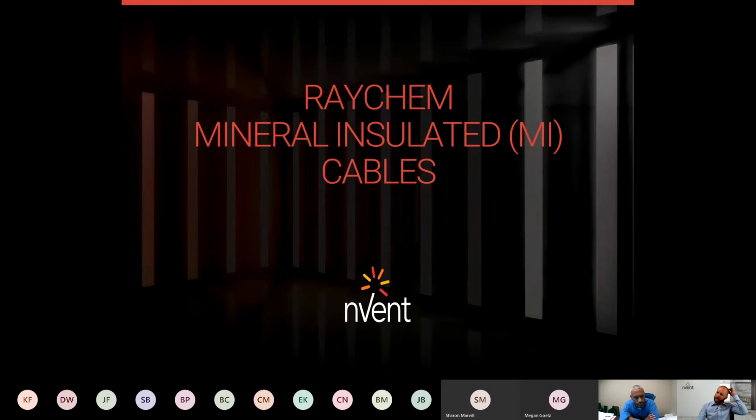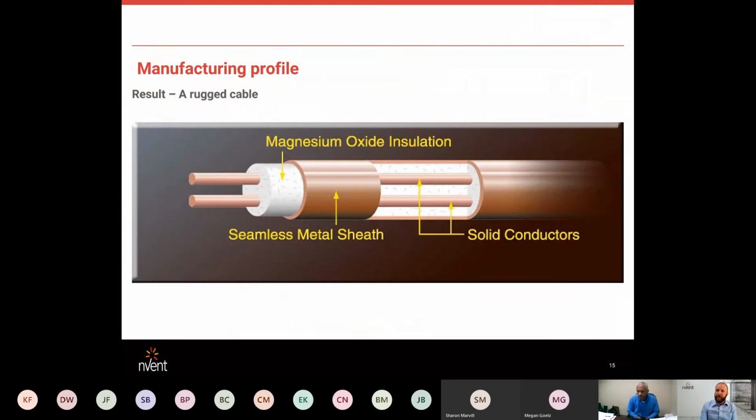So MI cables, which I just mentioned, MI standing for mineral insulated. There's a magnesium oxide insulation inside this tubing, I'll call it. It actually starts as a pipe, but acts as your insulating factor between the two current carrying conductors. Most of our MI heating cables are a separate technology outside of the self-regulating technologies. This is a series resistance technology, or a toaster wire. Just a resistor is what this is.